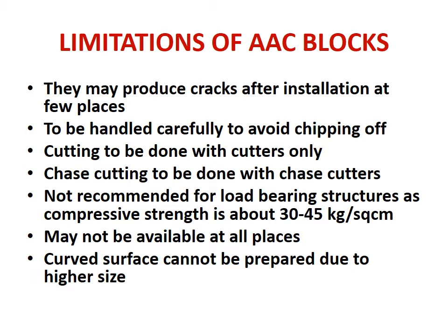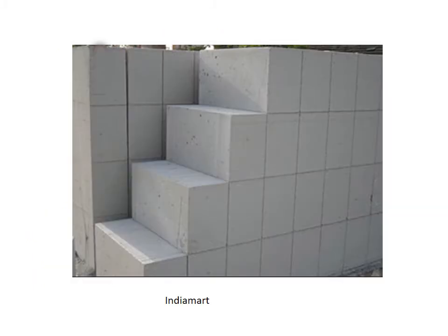So cartage is to be added if you are using them at interior places or bringing from a far away place. That becomes costly. And then curved surfaces cannot be prepared with AAC blocks because of the larger size. You see the photograph of AAC blocks. They are quite uniform.